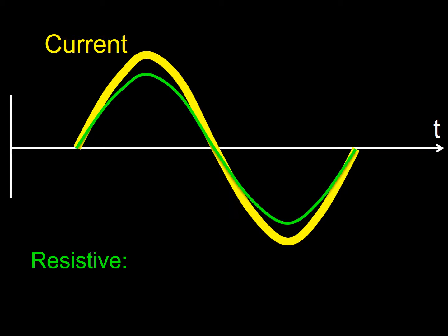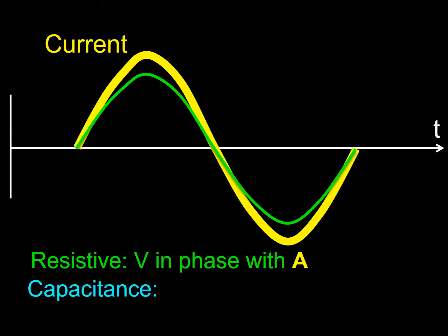So in this frame I am showing the relation of alternating current and voltage in a purely resistive circuit. The green line represents voltage. As you can see, when using a simple resistor circuit, current and voltage are in phase. If, on the other hand, we look at a pure capacitor circuit and plot voltage with the same time constraint, we find that voltage represented by the aqua sinusoidal line in this frame is displaced forward.